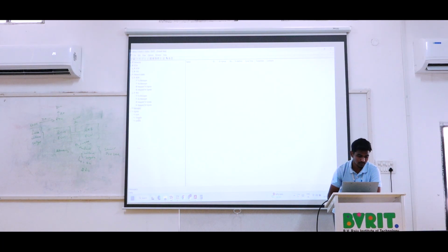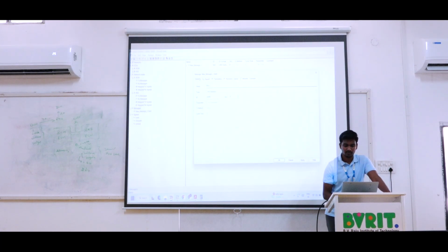Okay. So as of now we have created the lock, unlock and tailgate signals. After that we can create the message. Go into the message column, right click, give New, and then we can create the message with the ID number. The message is RK_1, and the ID number is 400. You can directly add the signal also, not an issue. But initially, what I explained was to first create the message and then give OK. But we are able to directly apply it.